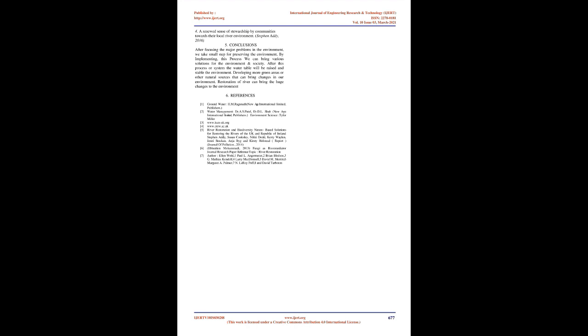Understand the connections between natural processes upstream and downstream, and work beyond the scale of individual reaches to consider riparian areas, floodplains, and the wider catchment. Target measures at the root causes of degradation, not the symptoms, and at the scale at which the pressures exist. Use minimal intervention wherever possible to reinstate natural processes so that rivers can recover by themselves. Evaluate restoration projects using robust monitoring techniques over long time scales, five years, to determine outcomes and inform future restoration. Stephen Addy, 2016.